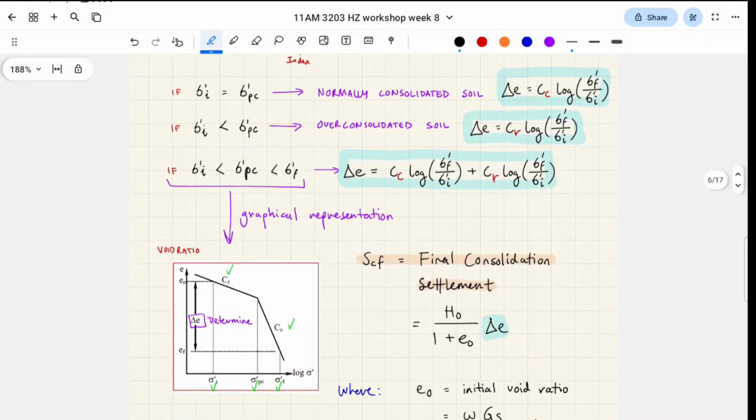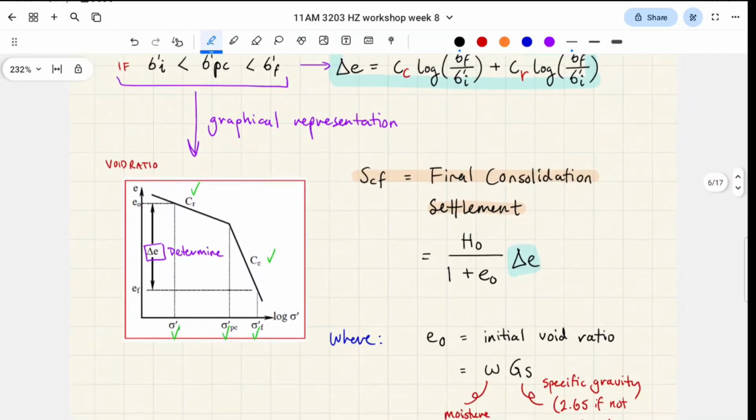This is a void ratio graph, where basically the idea is that the consolidation of clay depends on its change in void ratio. If you forgot what void ratio is, it's basically the amount of air in the little pockets between the soil. So as that gets reduced, that's what happens as your clay consolidates, or compresses, right?